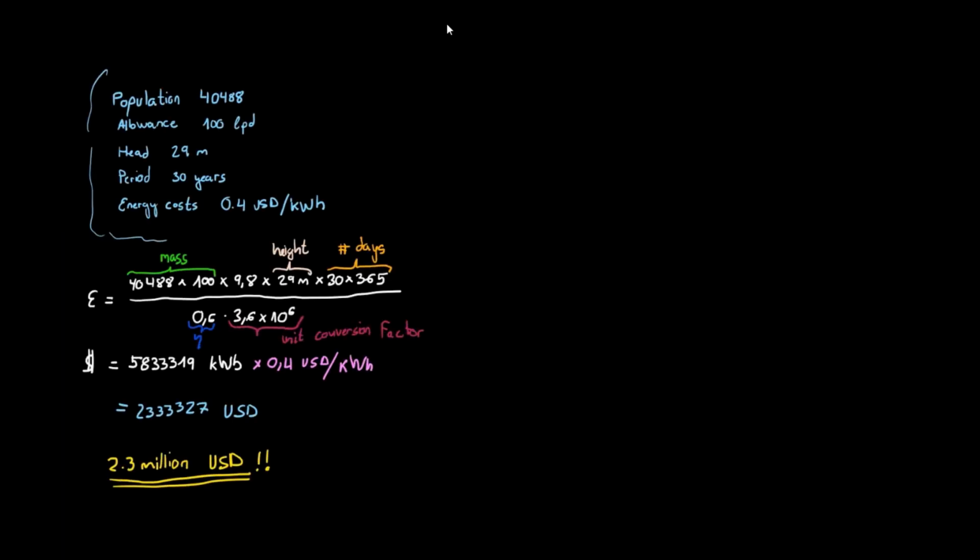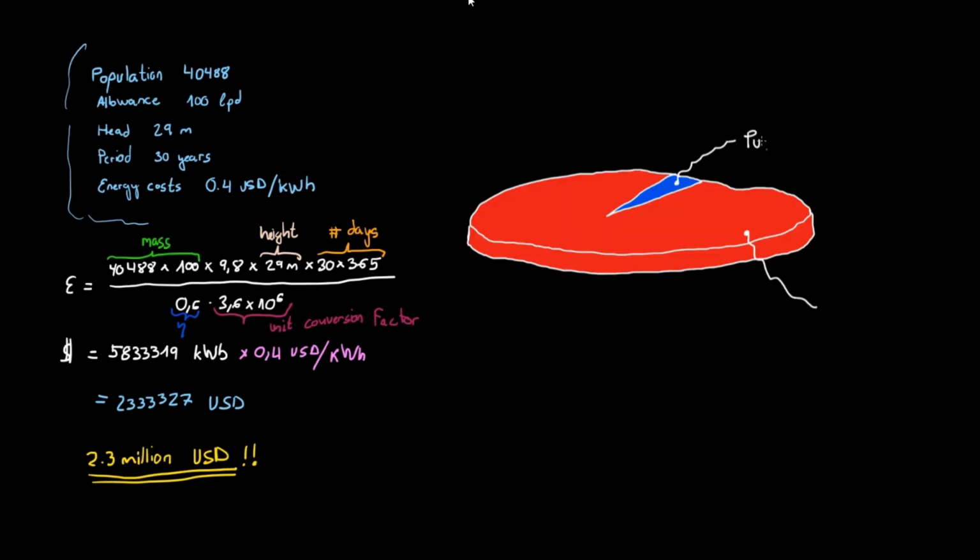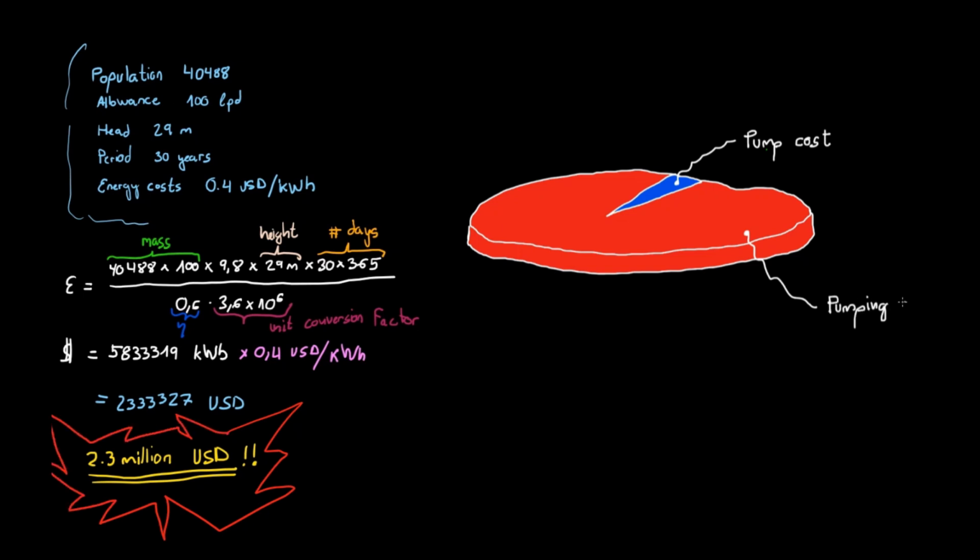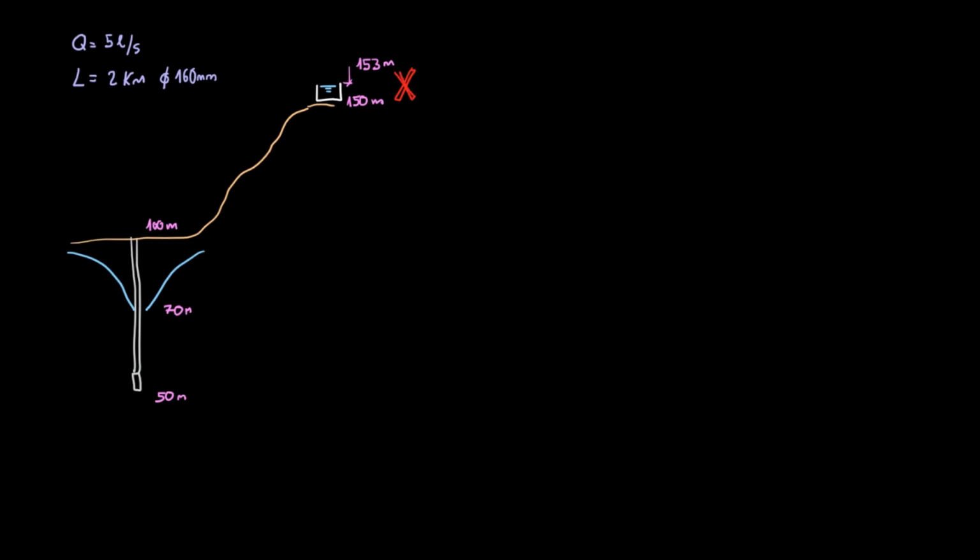One huge consideration is pumping costs. Considering the total life cycle, pumping costs dwarf investments in pumps, water tanks, and maybe even pipes. You should always try to cut down the pumping head by lowering the tanks as much as practical. In the case we have just calculated, if you lower the head by just 6 meters, you would get $500,000 in return.